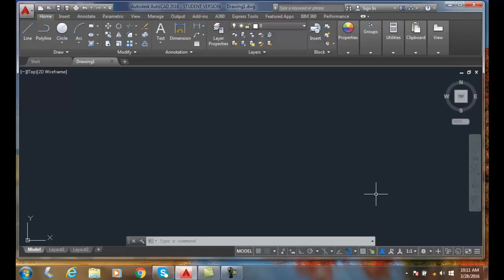For example, in mechanical drafting, we might use a style that's unidirectional, and it places a text style of, let's say, Roman S, which is a single stroke Gothic lettering, or perhaps an Arial. We might put the text in the center of the dimension line, break the dimension line, and we might terminate our dimension lines with arrowheads.